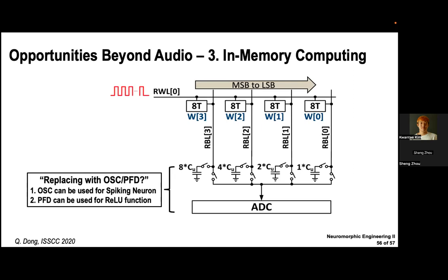However, if we implement this capacitor versus ADC part as an oscillator or PFD, then we can implement an oscillator-based spiking neuron or a PFD-based nonlinear activation function in the time domain, which is also promising and very interesting.